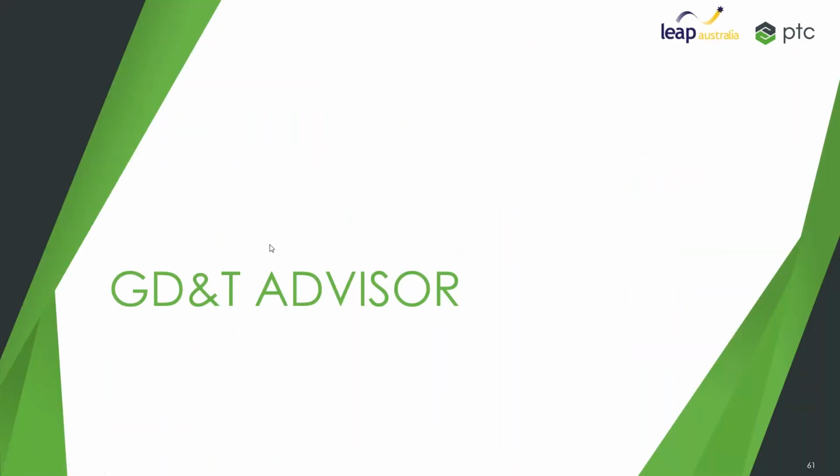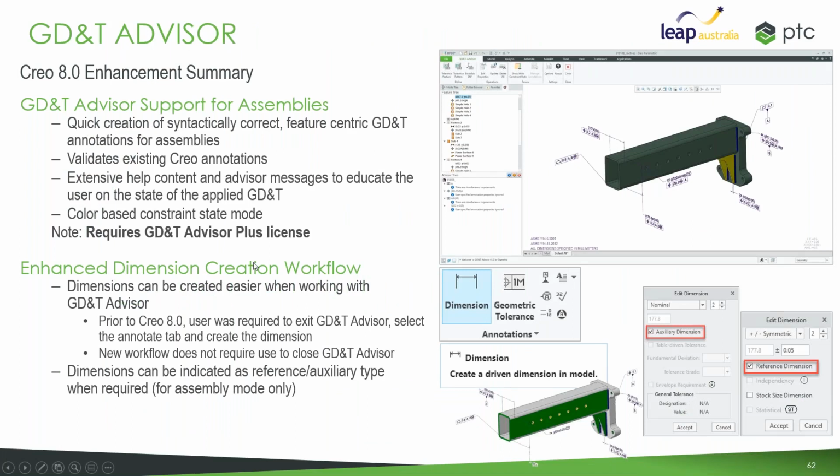GD&T Advisor. This was a new module introduced back in Creo 4 for doing your full GD&T checking on your models. Basically, it makes sure that you've got correct feature-centric GD&T that validates your annotations. Now what's there inside Creo 8 is the ability to do that on assemblies. Previously it was only for parts, but if you've got the GD&T Advisor Plus license, that's now supported for assemblies as well.